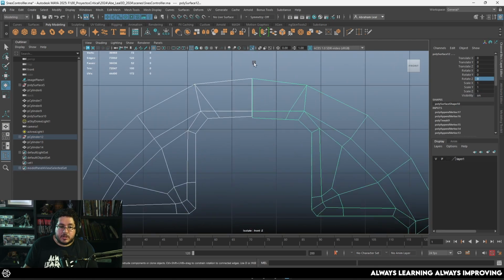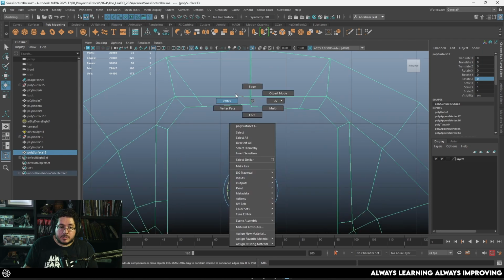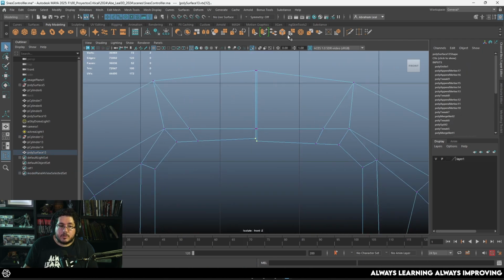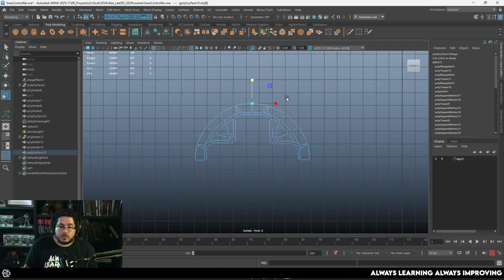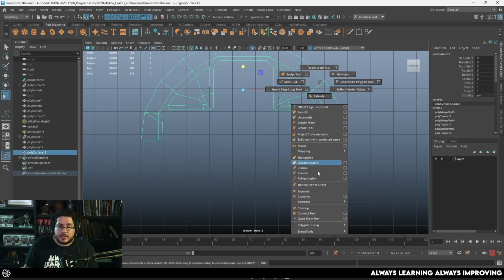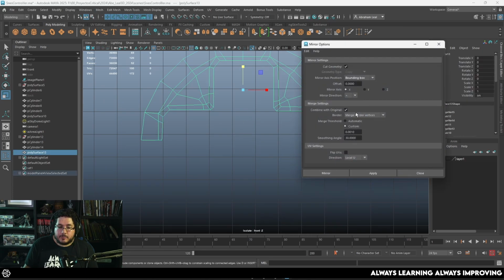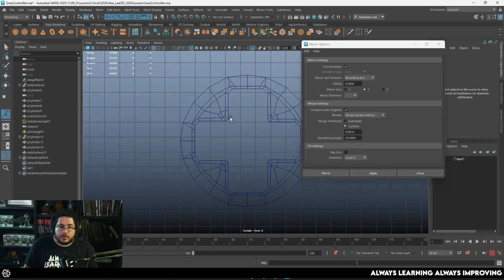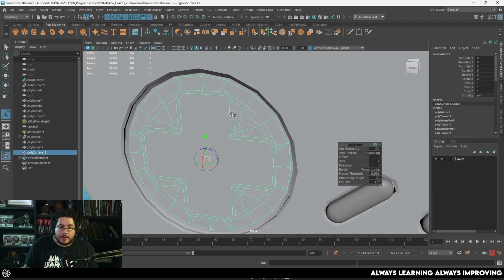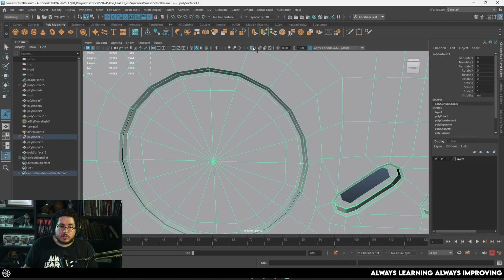And once that has been done, we combine both objects. We merge this to center. I would definitely grab all of these guys and flatten them out. Merge those to center as well, and merge those to center as well. Make sure all of these are perfectly straight. And in this case, it's easier, since we already have 1/2, to do a bounding box y negative mirror. And there we go. So that's it. We've created the proper shape for our navigation triangle right there.